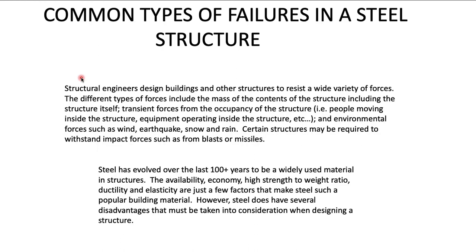It means structural elements designed and used in structures to resist a wide variety of forces. The different types of forces include the mass of the contents of the structure, including the structure itself, and the forces from the occupancy of the structure, that is, people moving inside the structure and equipment operating inside the structure. Environmental forces such as wind and earthquake, snow and rain, etc. Certain structures may also be required to withstand impact forces such as from missiles or ballast.